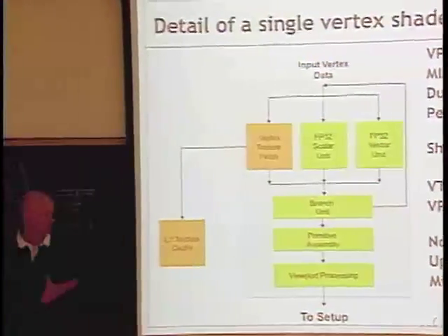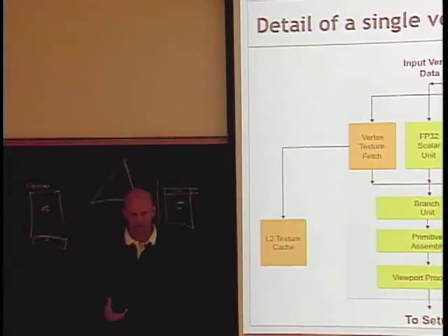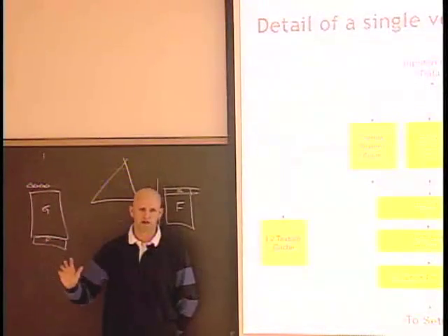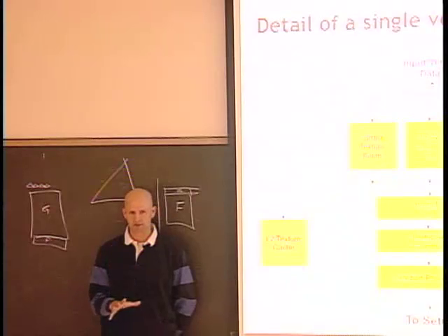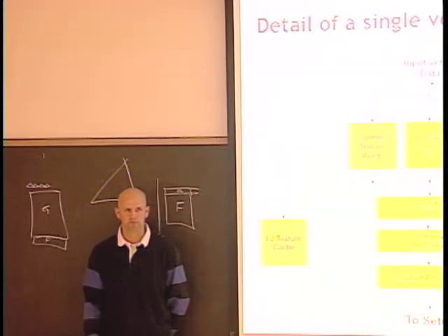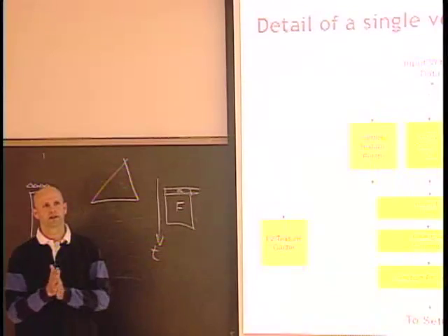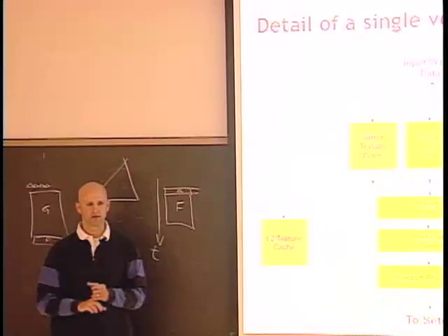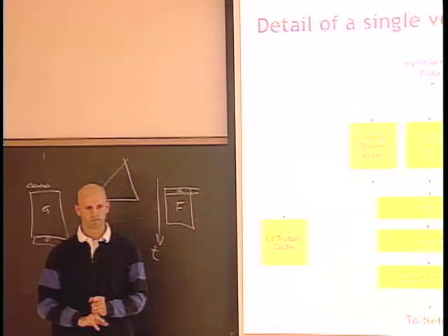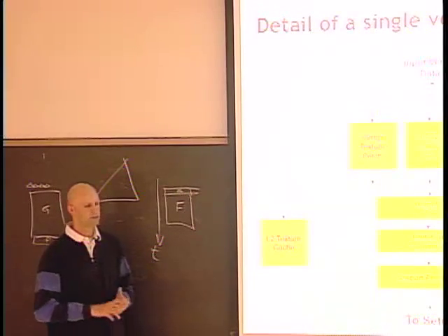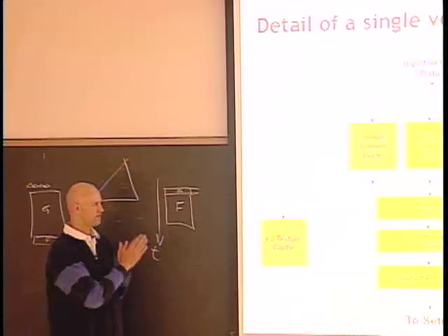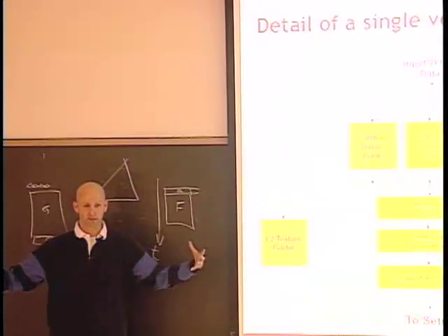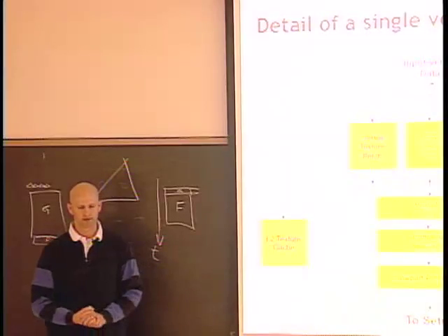It's fair to think of these processors as very simple compared to what you see on a CPU. They don't have any crazy out of order stuff or branch prediction. It's a very simple pipeline. On the other hand, there's lots of them, hundreds of them. I'll have a slide with a Seymour Cray quote: would you rather plow a field with 2 strong oxen or 1,024 chickens? The CPU approach is the oxen approach. This is the chicken approach, where we have hundreds of little tiny processors. Can we put them together to do something big?